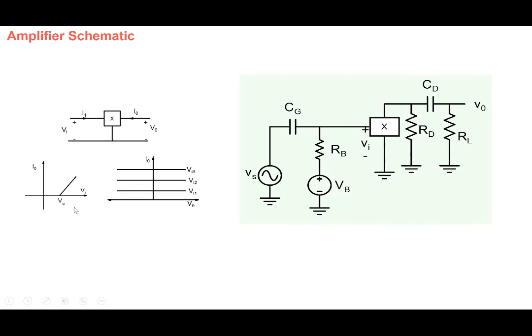And in the last lecture, we had seen that suppose the relationship between output current and voltage follows this particular behavior, where the current is zero until a particular threshold is crossed, and after that the current begins to increase linearly with Vi. And the output current versus output voltage is like an ideal transistor here. Then we had seen that in order to take care of this non-ideality, we have to bias the transistor using this particular bias voltage and RB, such that the transistor operates in this particular region.